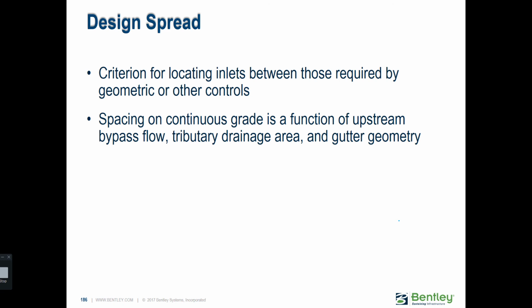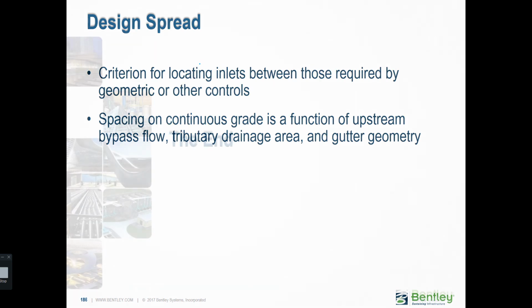So spread, as we talked about, is a big criterion for designing and placing our inlets. And we talked about the spacing being a function of upstream bypass flow, the area that is draining to it, and the geometry of your gutters.